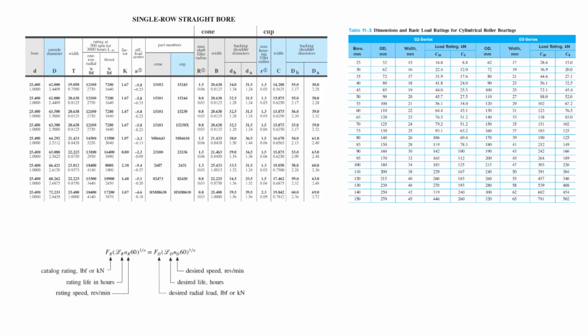And we haven't even really figured that out, right? So let's say we wanted to drive a car, I don't know, 20 endurance durations, which is a requirement I've seen thrown around. How do you quantify the number of rotations or the amount of reversing moment loads that you get on the tire? It's relatively difficult. Your car undergoes different corners, which results in different lateral loads. The normal load is constantly fluctuating everywhere, and it's really complicated. And then you have to convert all of that back to what your bearing sees in terms of moment, axial, and radial load, right? So this is one example of where I'd argue that defining the requirements or selecting the bearing and materials is a lot more difficult than the actual selection itself. So most of the work goes into that aspect of it.